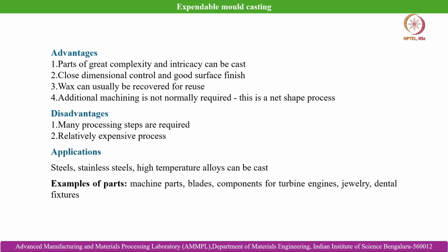So the applications are steels, stainless steels, and high temperature alloys like Inconel, IN718, CMSX. All these high temperature superalloys can be cast using this investment casting route. Examples of parts are machine parts, turbine blades, components for turbine engines, jewelry, dental fixtures, etc.